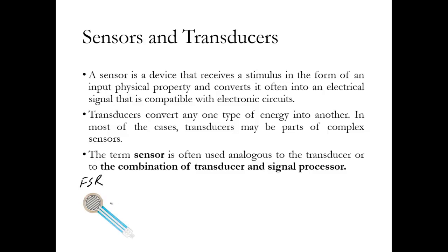So this is, again, you can say a force sensor or a pressure sensor. We press with a thumb on this face, and it changes the resistance of this, and accordingly it can be detected by a Wheatstone bridge, which can find out the amount of pressure that has been applied. So this is, for us, a sensor.